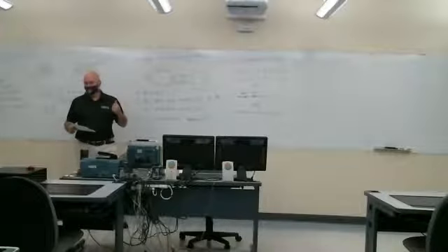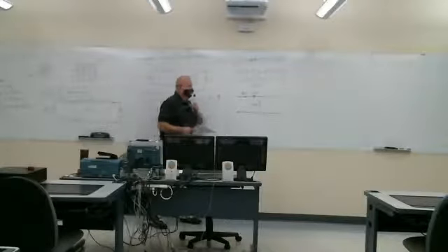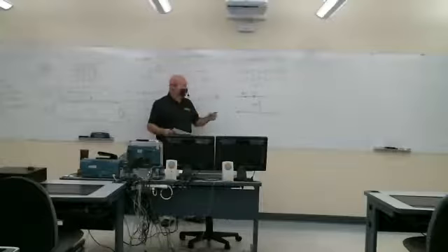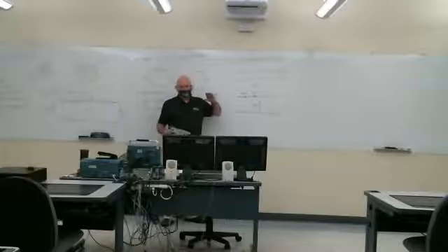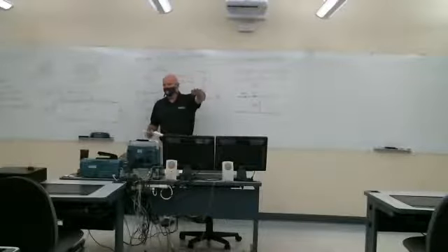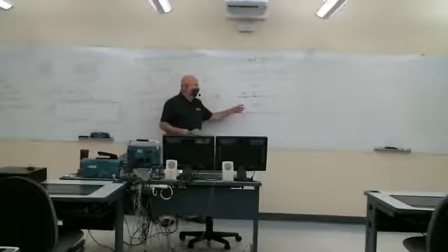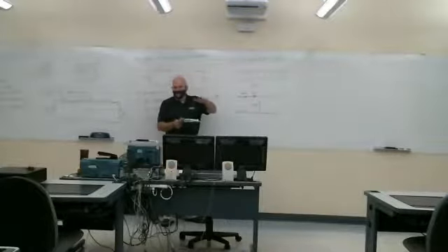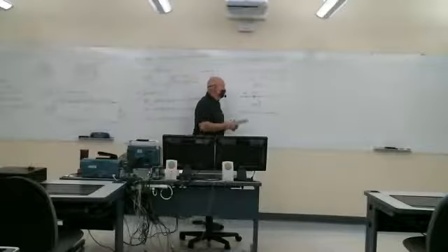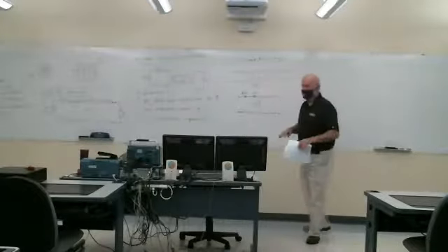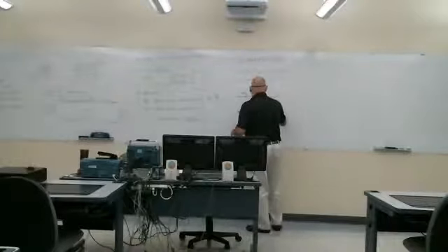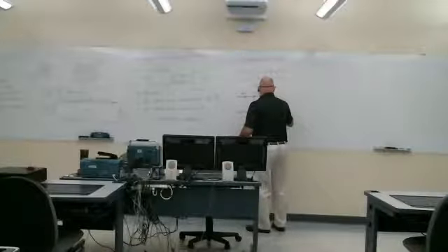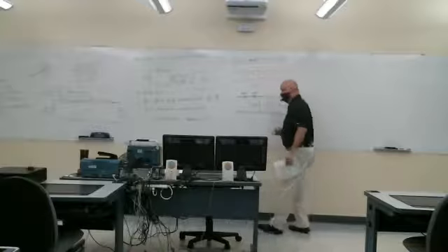You could use a resistor there, but the equations actually are a little simpler when we write them in terms of this conductance instead of the resistance. Now this is a completely different resistor than R prime is. R prime represents the metallic resistance in the wire. G prime is the resistance between the two wires. And anytime you have two separated metallic conductors, there's a corresponding capacitance between the two conductors.